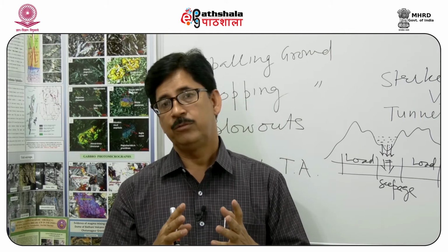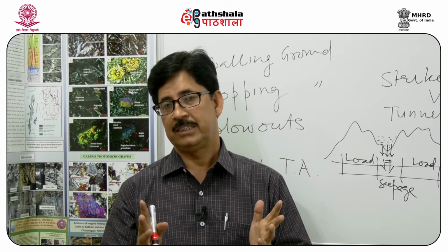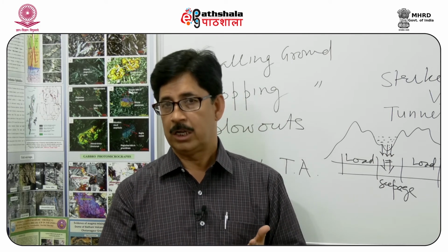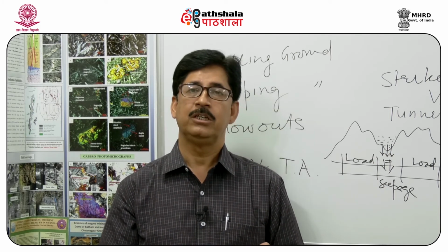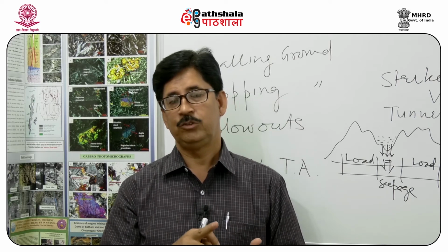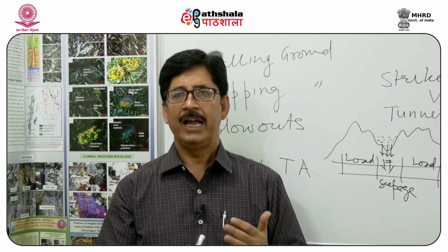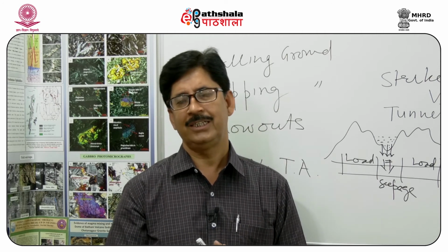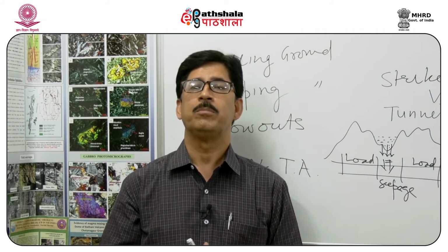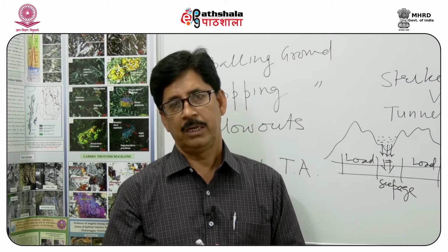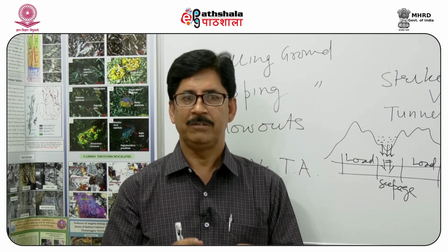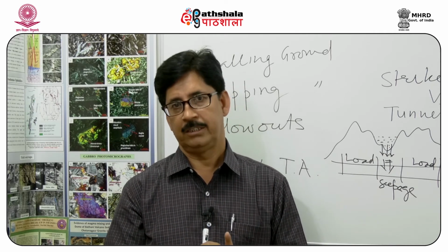For this, we have to go for overall analysis, starting from unconfined compressive strength of the rocks to the RQD, that is rock quality designation. We have to analyze joint spacing, joint condition, joint alteration, and ultimately we may have to use any two of the important rock mass classifications, that is rock mass rating system or rock mass quality system. All these rock mass classifications have incorporated all these important factors related to the joints.